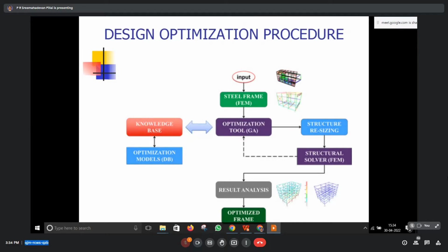I told him to revise the wall thickness to 17 centimeter. Instead of giving 12 centimeter, make it 17 centimeter. Then he was asking me, sir, why are we getting only 12 centimeter in the design? And the software is also correct. Software gives the design 12 centimeter. Software is correct, but software is not sensible. This I always tell the designers. That is why whenever I am entrusting someone to do the design and bring to me, only after checking can I give it to the client. Then the first thing I see is the design dimensions.